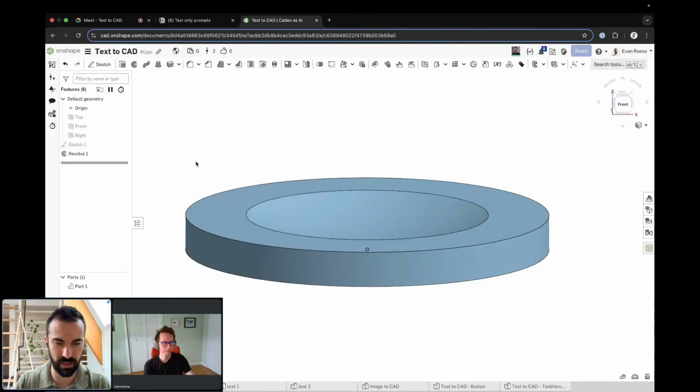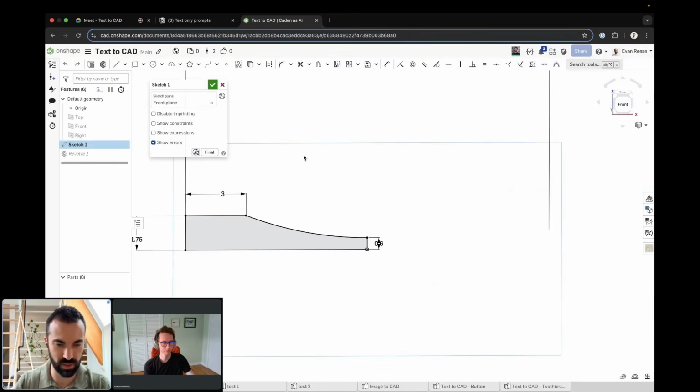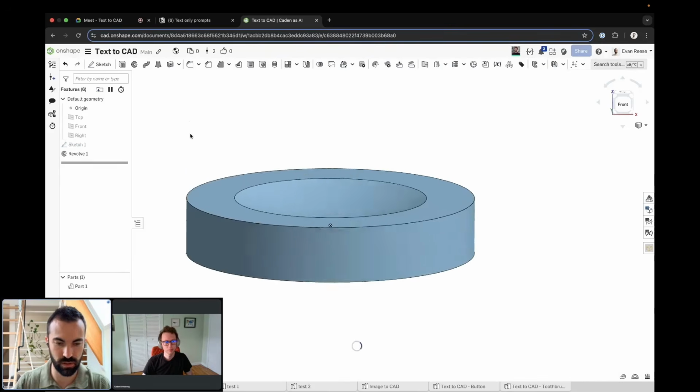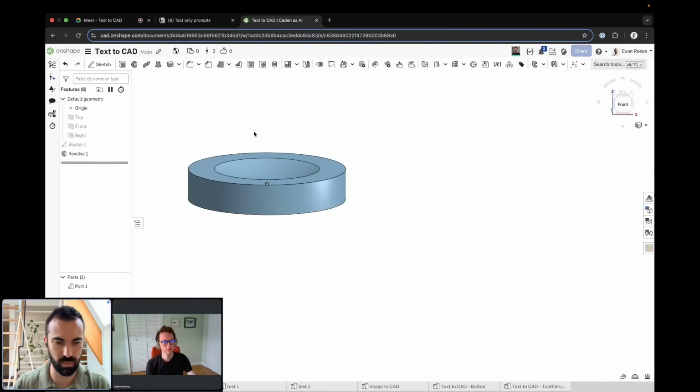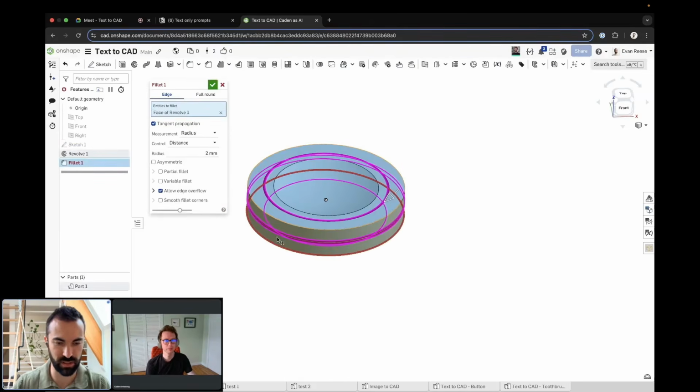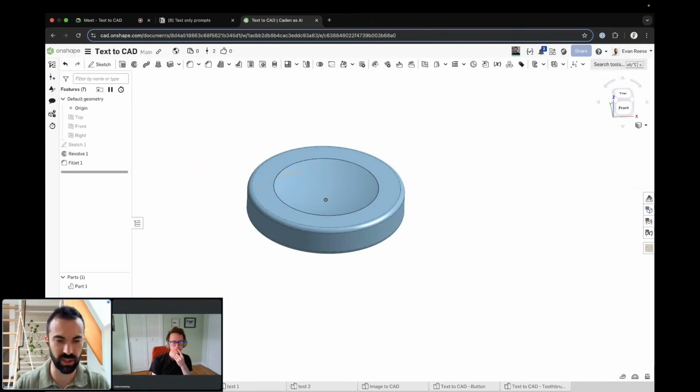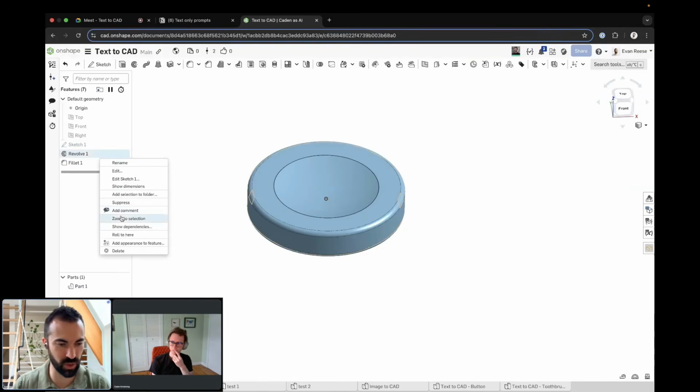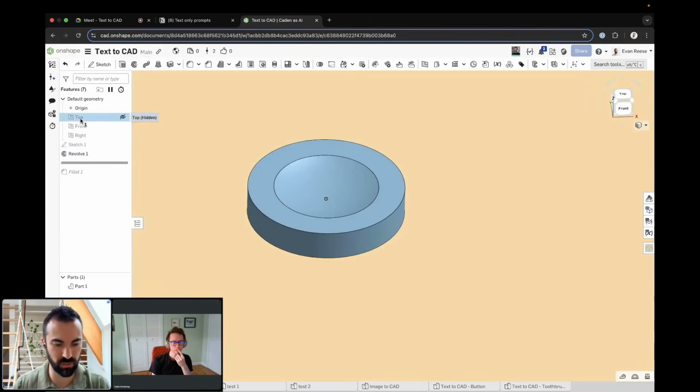Normally I'm a proponent of mirroring objects, not sketches, but in this case, it's so simple that I think I'm just going to mirror the sketch and revolve the whole thing. Make that construction. All right, so I'm starting to get a button. Buttons have fillets, which I'm inferring is probably a good idea based on my understanding of what a button is, not because of the prompt itself. But I first need those holes.